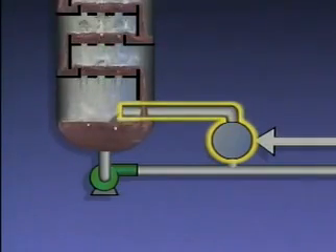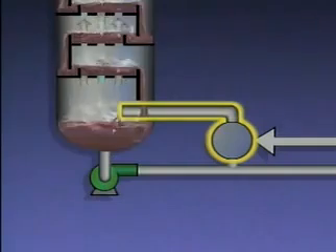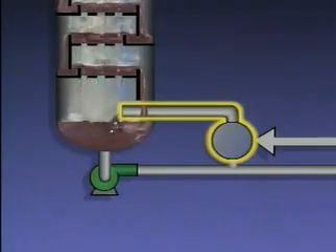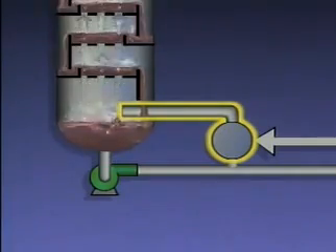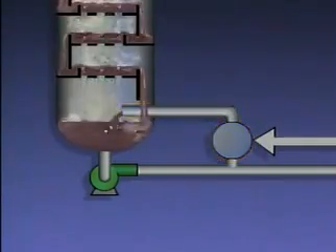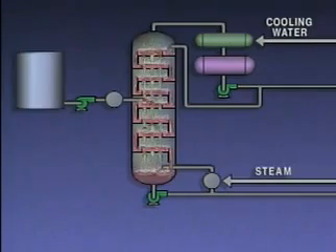The hot vapors cause any lighter fractions in the liquid at the bottom to vaporize and move up the tower. This reduces the amount of lighter fractions in the bottom's product. The reboiler provides the major portion of the heat that's required to make the distillation process work. In the type of system we've been discussing, the heat supplied by preheating the feed is not sufficient for proper distillation. The reboiler is needed to provide enough additional heat to vaporize the lighter fractions in the tower so that